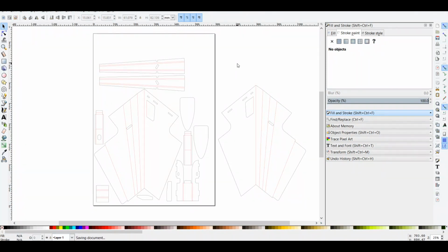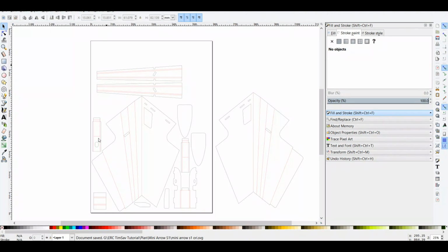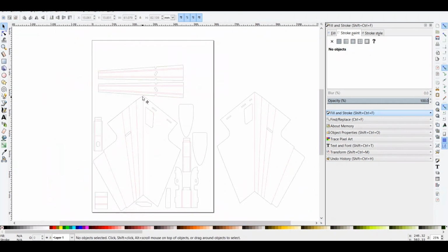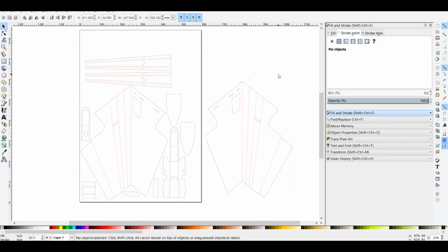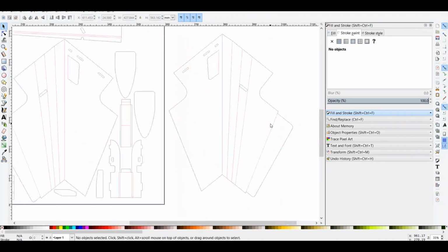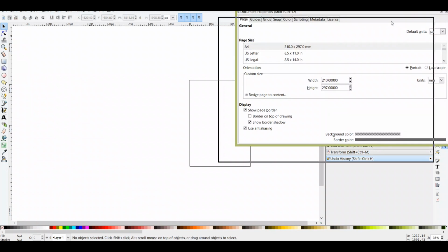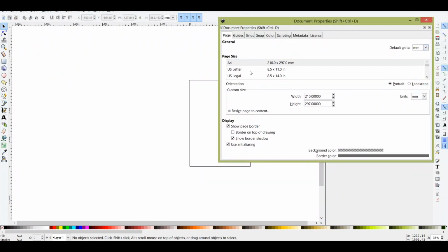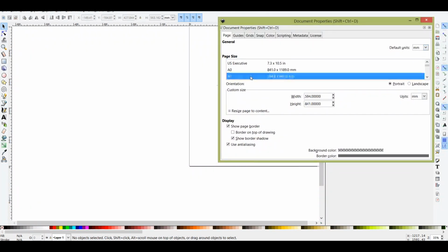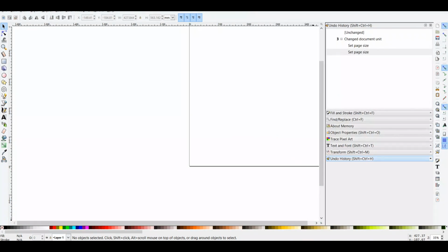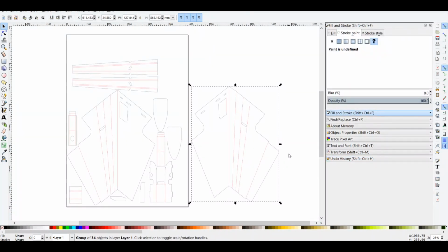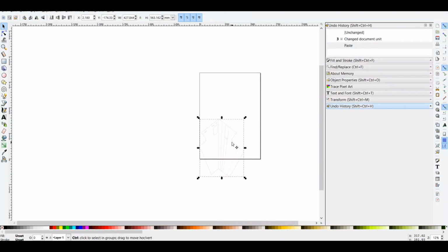Now I'm going to Control S save again, and as you can see, all the parts over here are for sheet 1. And then I've got this right wing processed as well. Open a new workspace, and please always remember, whenever you open a new work file, select your size. Alright, choose mm here and A1 size. Then go back here, select your right wing, copy, then put it over to the new sheet.